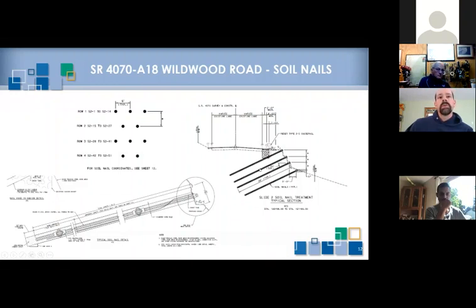So if you're looking at a cross section, you see what a circular failure might be. Then you basically have these somewhat perpendicular to that plane to nail the front material to the back, but also provide that shear reinforcement to that slip plane.